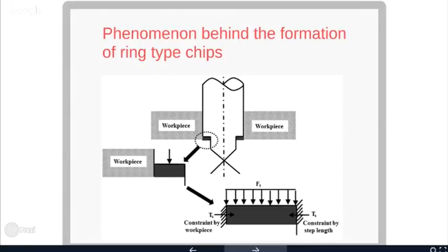It's not a semi-molten state. Some sort of, you may call it, semi-solid. But semi-solid starts when the temperature is above the lower crystallization temperature of the material, and the lower crystallization temperature of this aluminum is close to 450. Here, the rise in temperature is not more than 250, so it won't create any metallurgical changes.